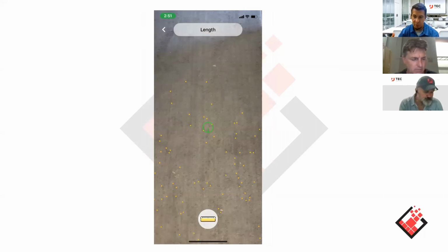So if you're at a job site and you want to remeasure and make sure that you have that 2% slope you were aiming for, you would take one height measurement at the back end of your property or the patio, wherever that may be, and walk towards the front or the side, wherever you're going to take the actual reading. Between those 2 points, the app will calculate the percentage of slope and the distance. This is something we wanted to have available last year, but it took a little bit to get going. Now it is active on this app and available to you, so definitely play around with it when you download it and get it active.